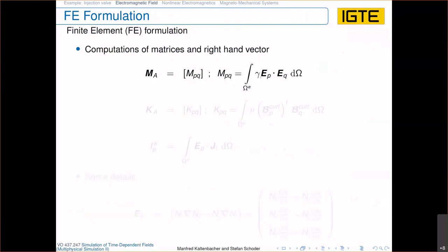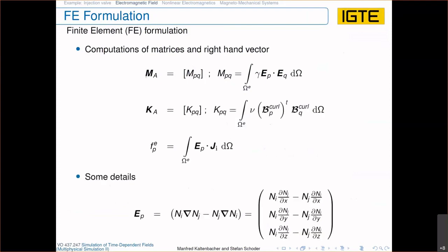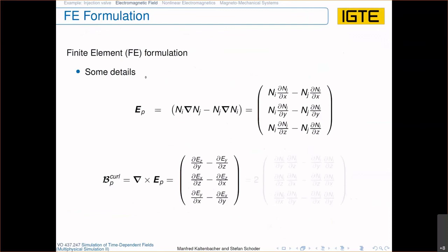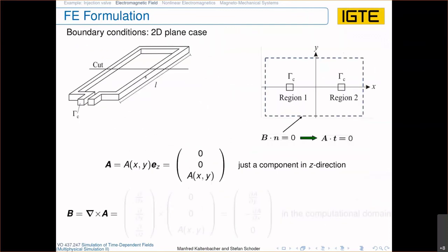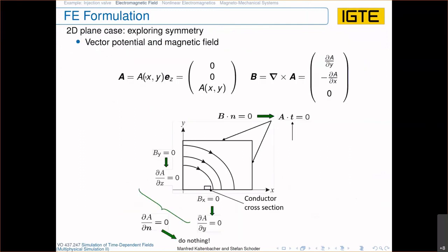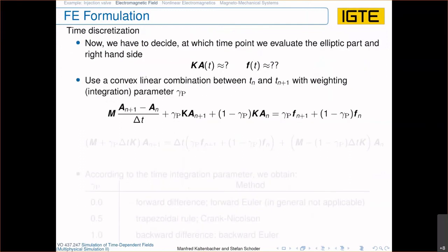In air, for example, the conductivity is 0, and then you would have 0 entries on the diagonal, so you cannot solve your system. So in this case, for the quasi-static electromagnetic field computation, this is not a choice which makes sense in practice.